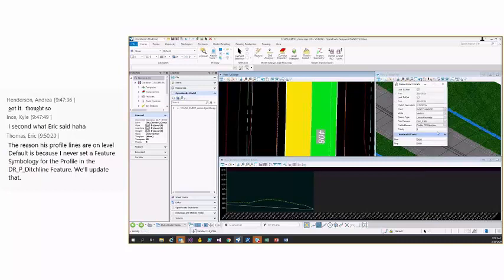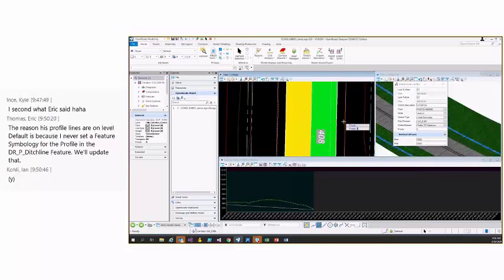I think this was the one that went the whole way. Hopefully it is. Alright, so vertical offset, we don't want to offset. We already have our ditch profile that we projected, so we wouldn't want to offset any more than that, because that's what we were trying to make our ditch match to, right? So we'll leave those at zeros.